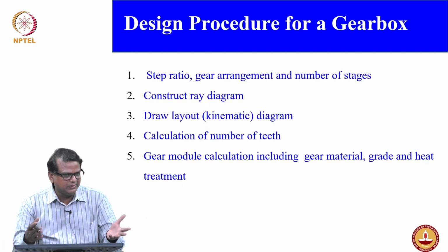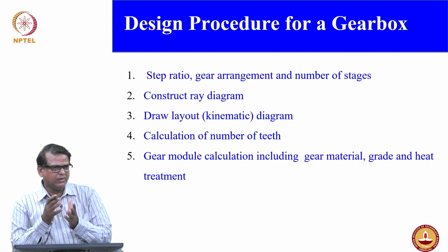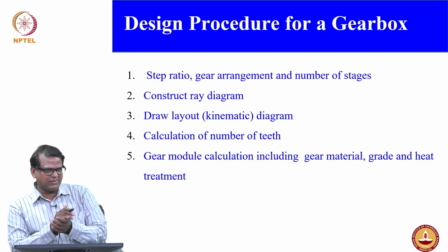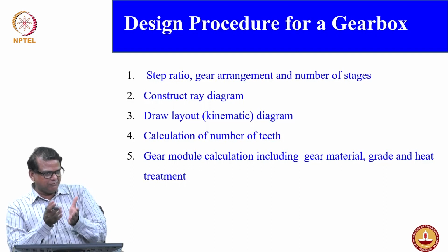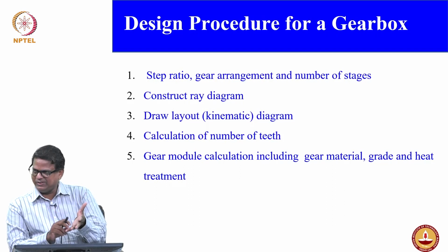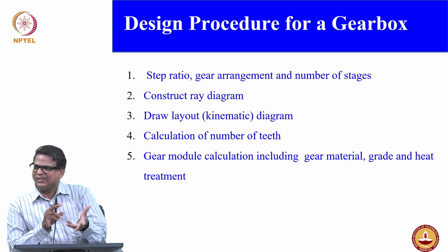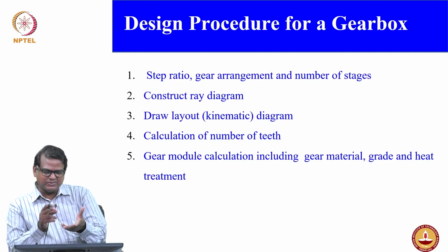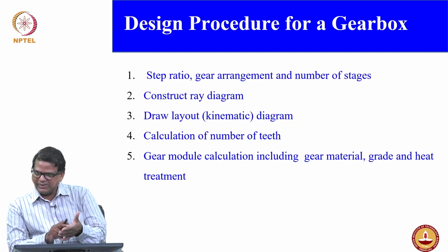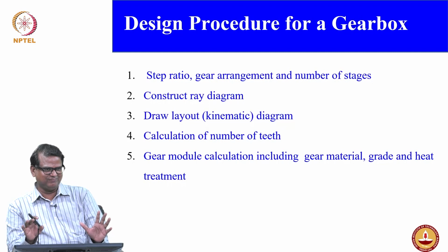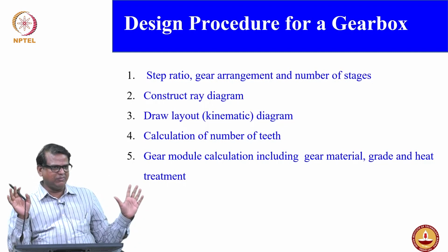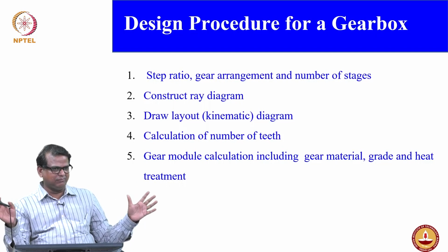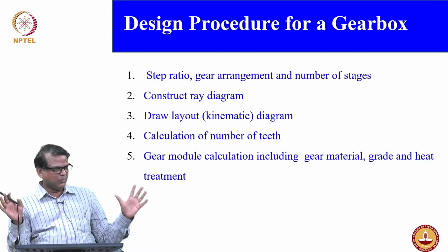Based on the power and torque, we are going to design a gearbox. In your UG course, normally the module is given, power is given, then you do the calculation. But as a design engineer, you have freedom. You have to select the material, design the gearbox, design your shaft, do the bearing selection. Everything you have to do here. No information is given. I only know the engine specification, the size of the vehicle and the vehicle weight.